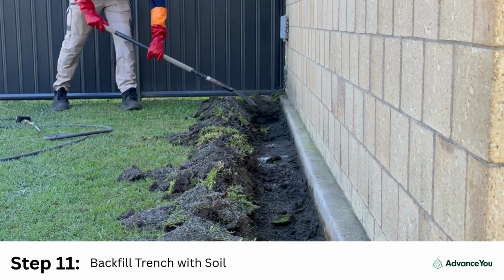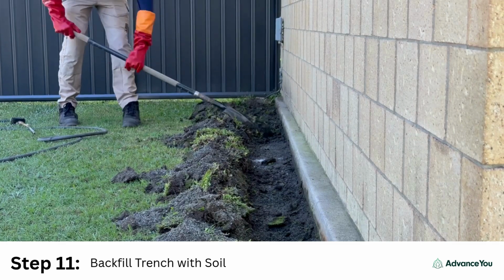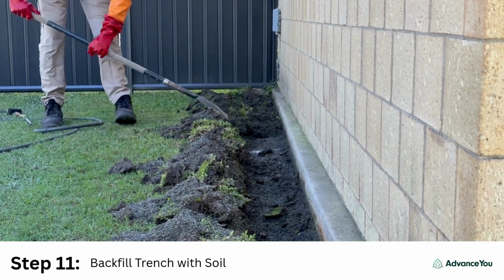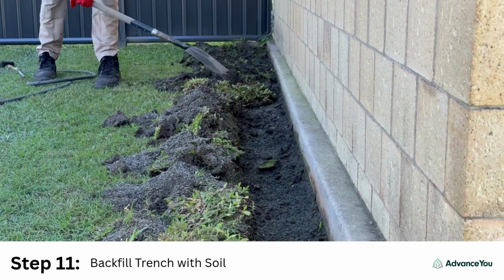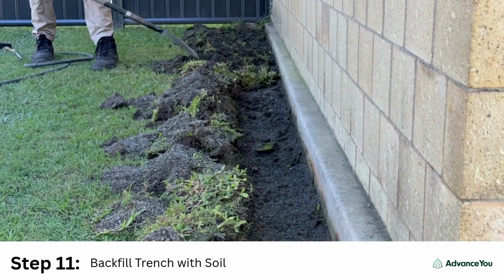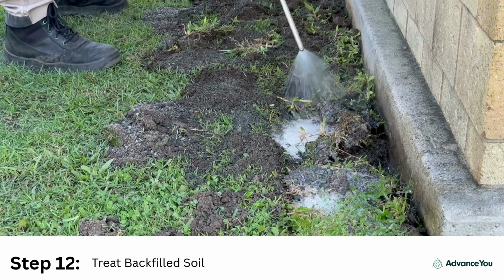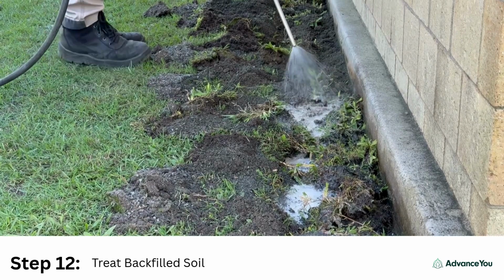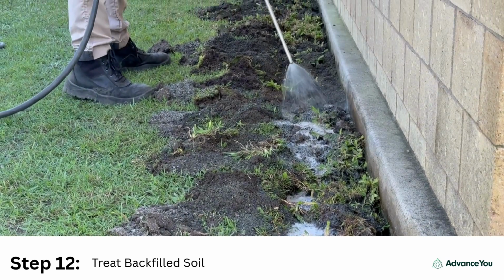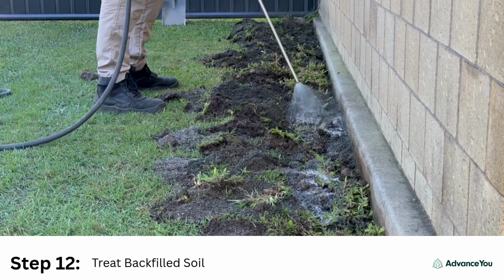Backfilling is achieved by pushing the existing soil back into the trench. In this case study, Shane only needs to backfill the trench once. Once the backfilling is complete, the soil will then need to be drenched with termiticide as per the product label. This ensures no gaps and a consistent chemical treated zone.